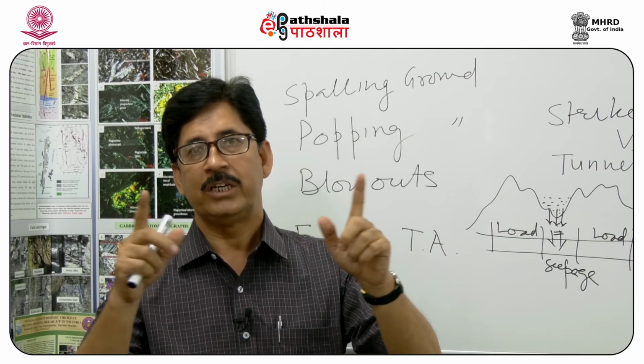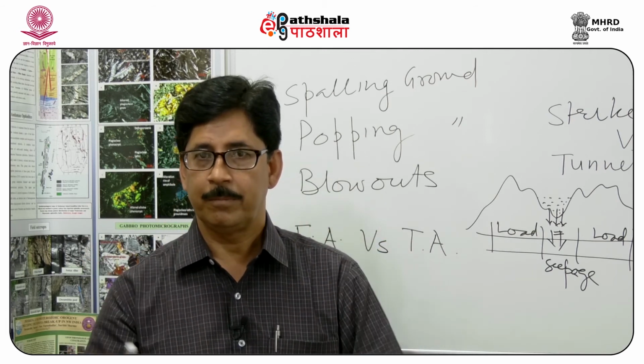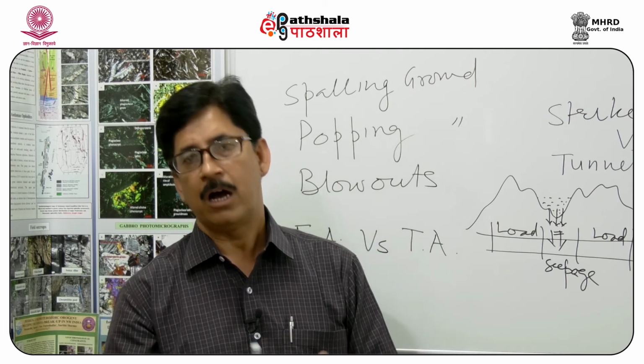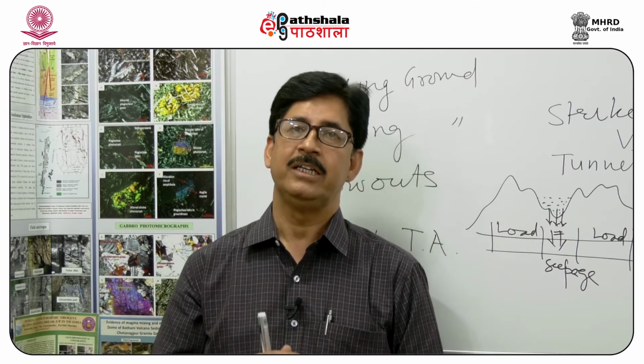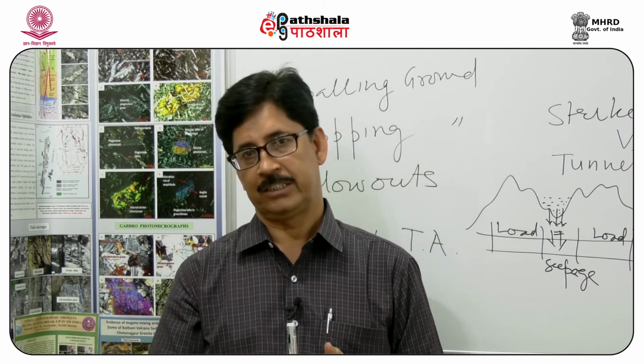Depending upon rock mass quality, we may go for full face excavation. That is, we are going to excavate the whole diameter or whole face of the tunnel, or if the rock mass is weak, then we can go for benched excavation.